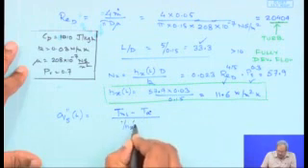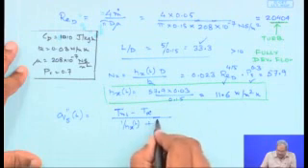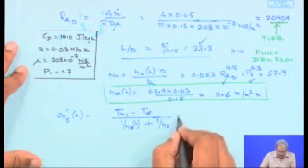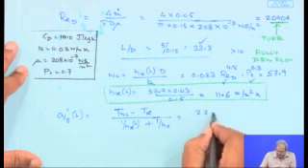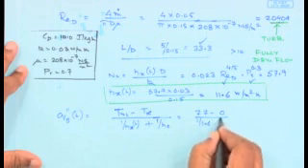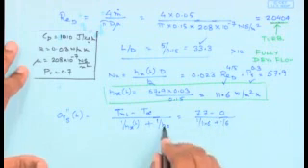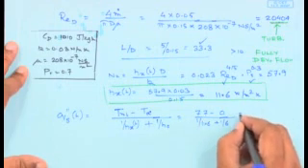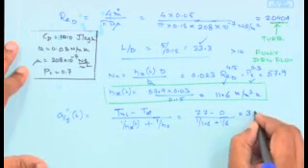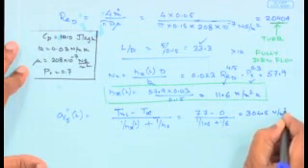So this would be 77 minus 0 divided by 1 by 11.6, the value that we have just obtained, plus 1 by 6, the value of the heat transfer coefficient which is provided, and this would turn out to be 304.5 watt per meter square.